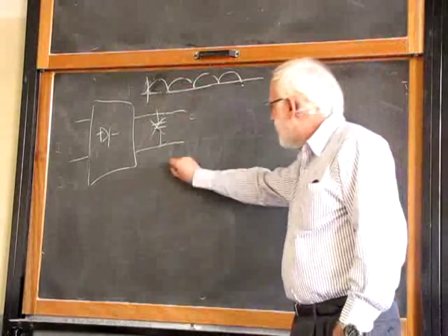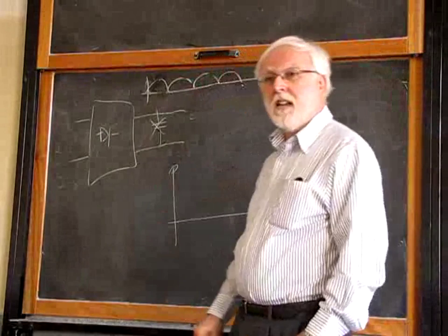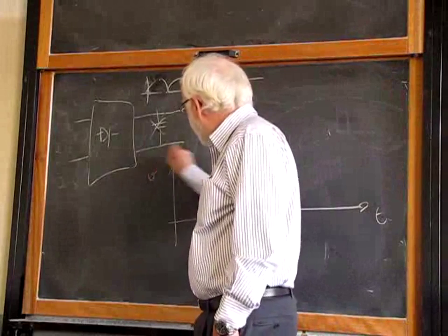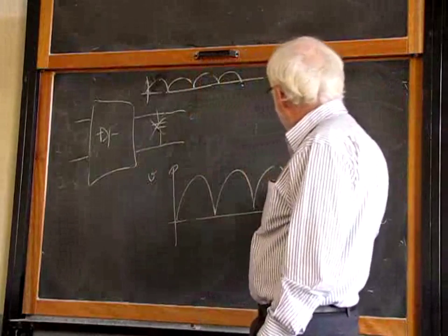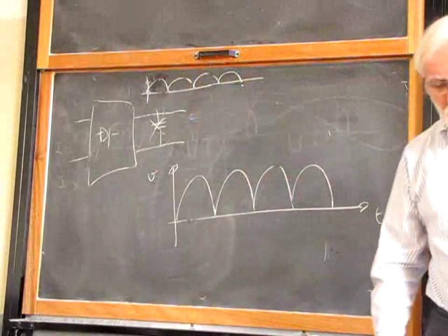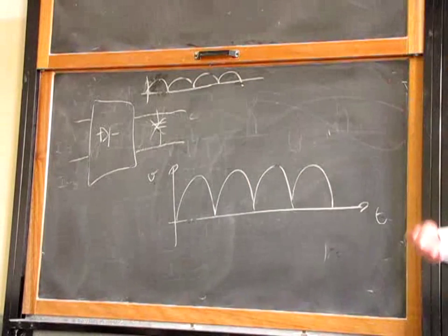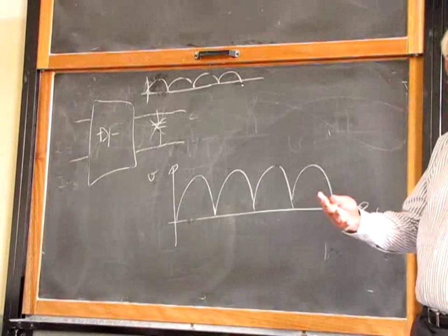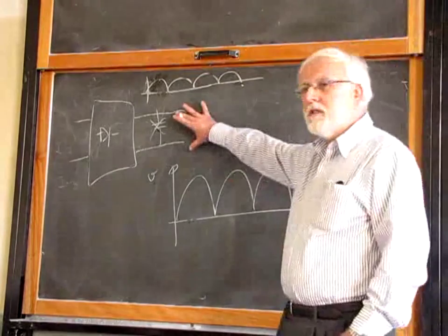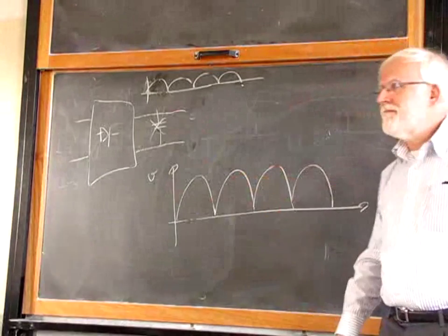And we started to look for a high efficiency circuit, so it means a switch mode converter, that is able to take this varying voltage and convert it to a constant DC voltage. We know three topologies by now, four: buck, boost, buck-boost, and so on. So we said, okay, let's try to put here a buck converter in order to regulate this rectified waveform.